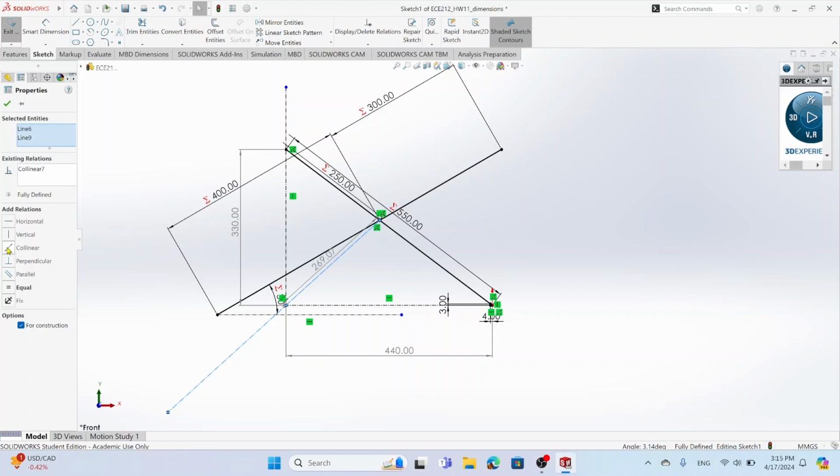Okay, so this line represents the perpendicular line to the velocity VD, because remember, the velocity is always perpendicular to the line from the IC to the point. So that was this one for the first bar. But now for the second bar, that's also perpendicular to this one, because VB is the same, VD is the same. Okay. What else do we know?